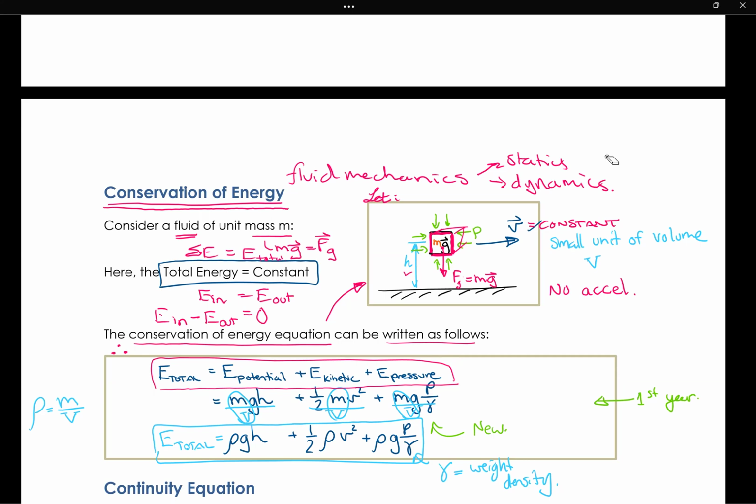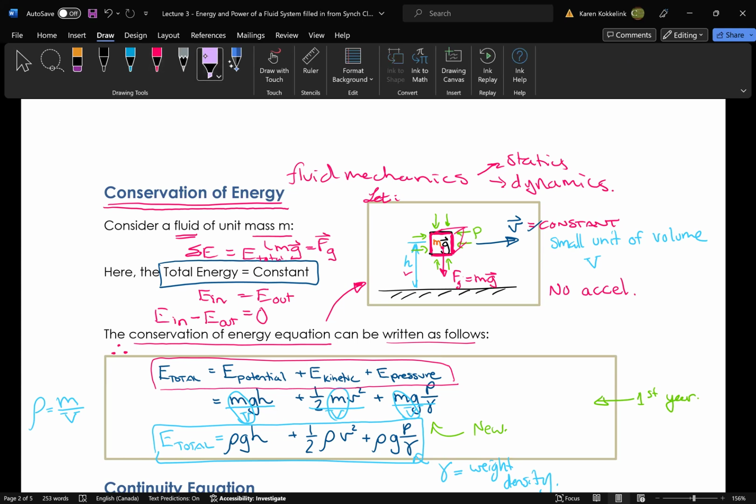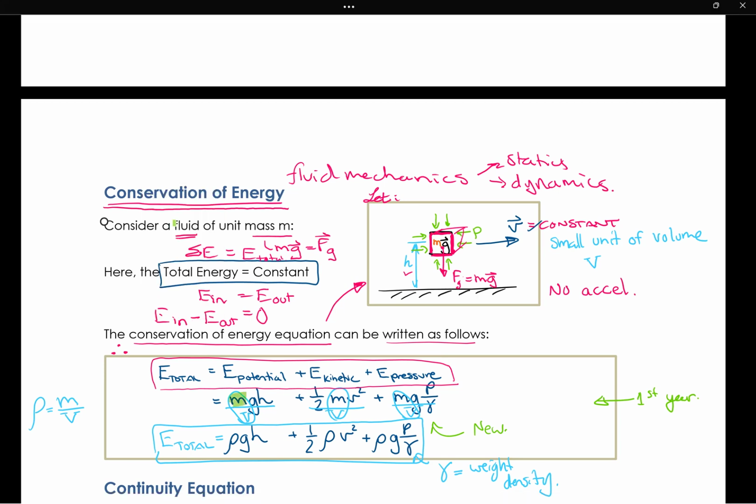With a basic knowledge of mechanical engineering, we remember that there is an energy in the form of any mass that is elevated. The energy in the form of any mass that is elevated is called potential energy. And that potential energy term is always relative to the mass that has that potential, the height that potential is from the ground, that's h, the mass that it is, and then acceleration due to gravity, which is 9.81 meters per second squared here on Earth.